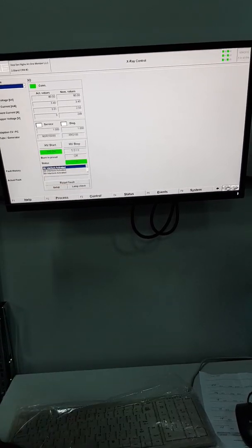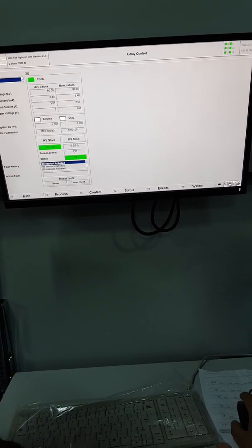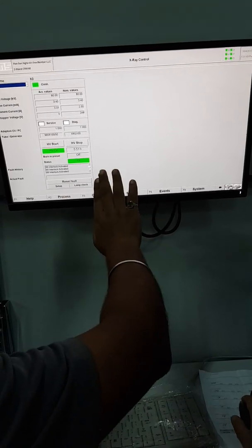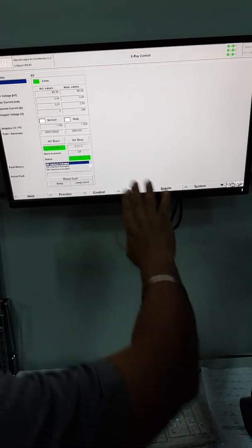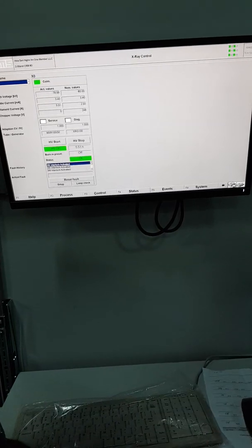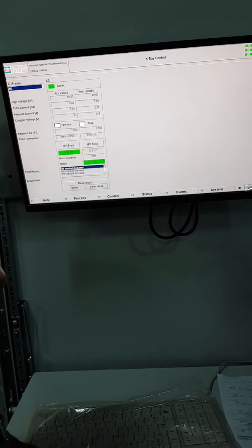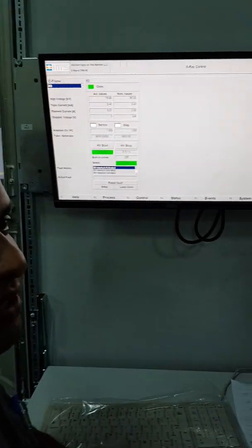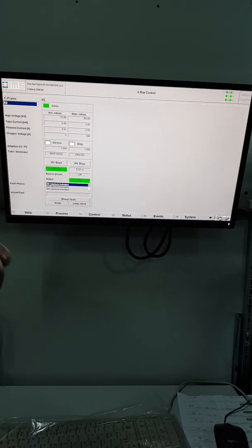Other than 99 interlock, there is another fault: 63 power supply error. That is normal, you clear the fault and that will go. Don't go here and there, because it is very crucial. If you don't know, then it may break something. It's very costly, you know.